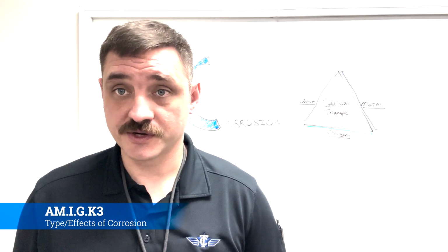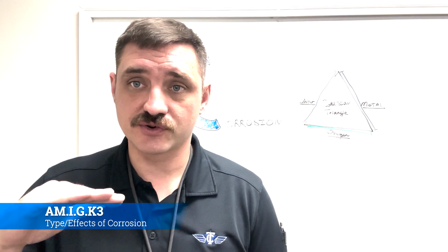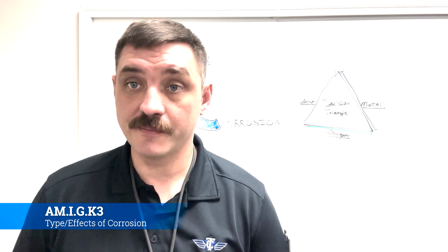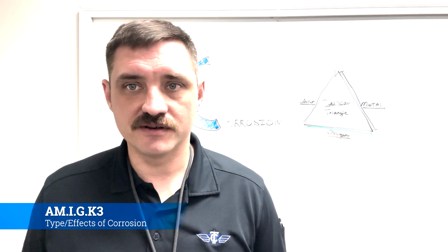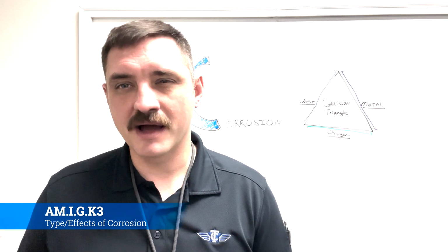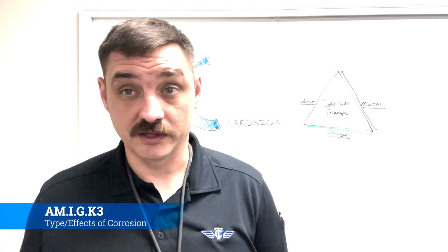Okay, so pitting corrosion. Pitting corrosion is probably the worst on a metal because if it's under strain, that becomes a weak point in the metal, and that's where breaking will happen. But essentially pitting is just that. It creates pits on the metal. Aluminum is really bad about this. You can definitely have it on just about any form of metal, but aluminum seems to really pit, at least in my experience, whereas iron definitely pits really, really bad as well.